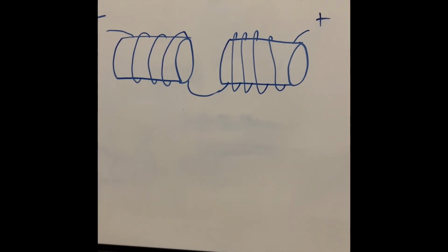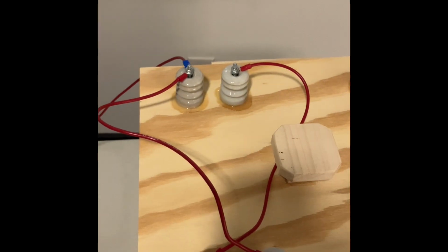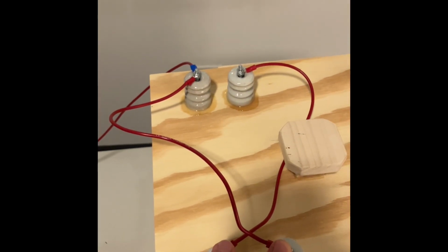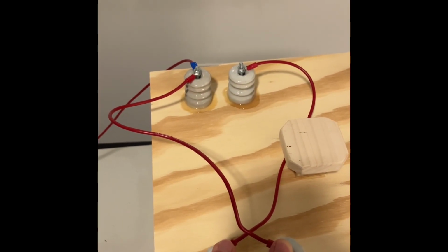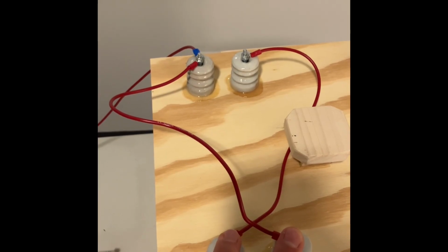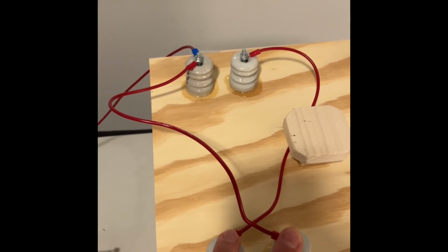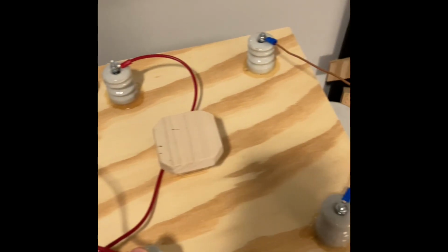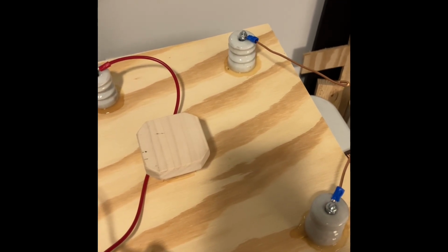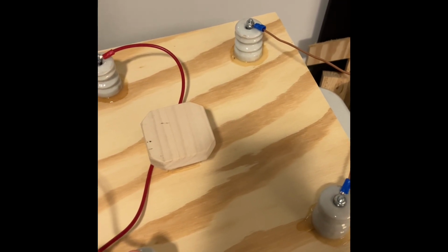Then when I started thinking about it, you have to hook it up like this, and then you get your strong output effects. In the primary coils, you have to hook it up so that it induces currents in the secondary coils which move in the same direction and don't fight each other.